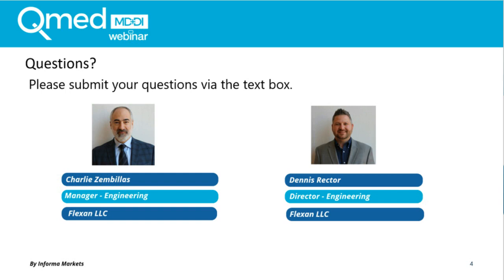All right, thank you, Dennis. Our next question asks, would gamma radiation affect the silicone materials? That's a great question. So that is yet another reason why you would want to post-cure an extruded silicone tube. So gamma will affect any silicone extrusion or molded part because it continues to cross-link the material. So you can have dimensional changes if you don't post-cure it in a convection oven to stabilize the part.